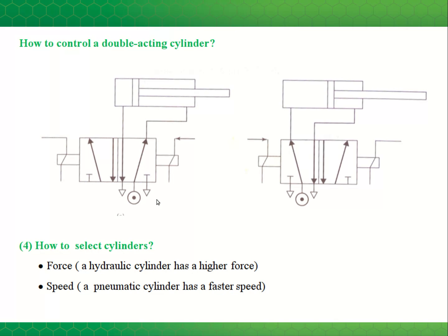So one advantage of a 5-2 valve is that you can have a vent placed close to the cylinder so it can retract more quickly.